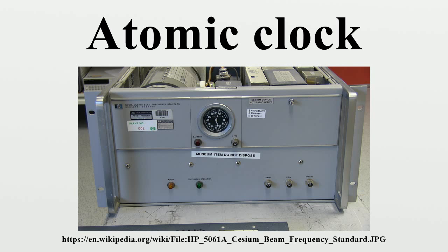Atomic gas cell standard. The atomic gas cell standard builds on a confined reference isotope inside an RF cavity. The atoms are excited to a common state using optical pumping. When the applied RF field is swept over the hyperfine spectrum, the gas will absorb the pumping light, and a photodetector provides the response. The absorption peak steers the flywheel oscillator.